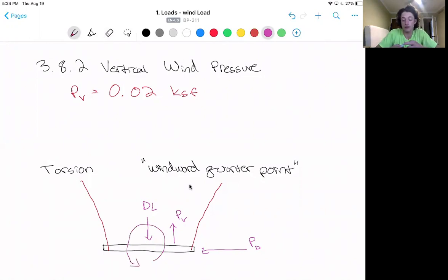And what we discussed the previous two sections was that the thesis that is linked in this page went through the calculations and determined that any bridge less than 80 meters and with a 5% design sag is not at risk for torsional instability. So we won't go into that process now because it's more complex. But if you were interested, you can read the thesis. And coming soon later in this course, we're going to discuss lateral stability, and we'll discuss actually how we would take these loads and figure out if they are going to overcome the dead load here, and what we need to do to mitigate this.